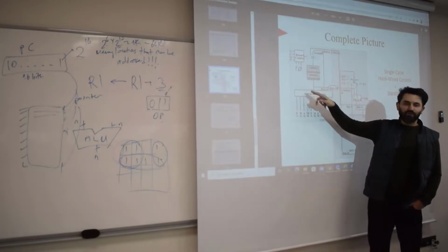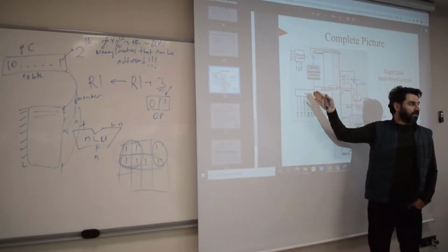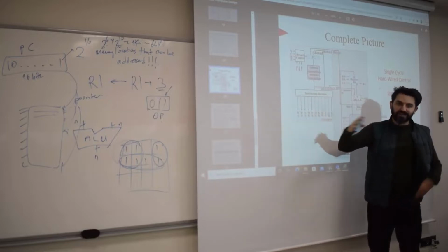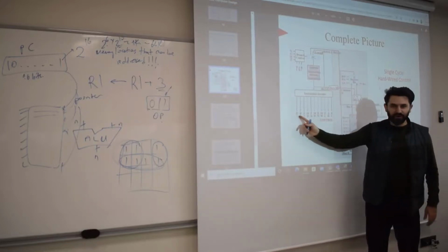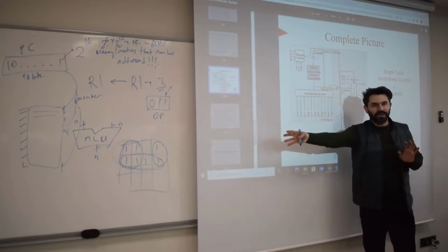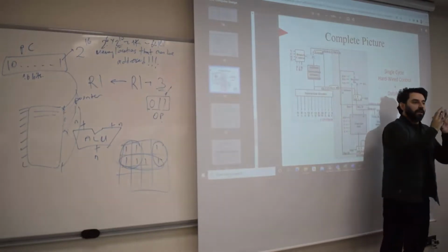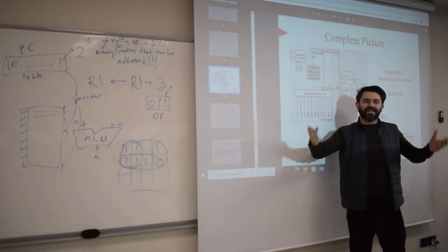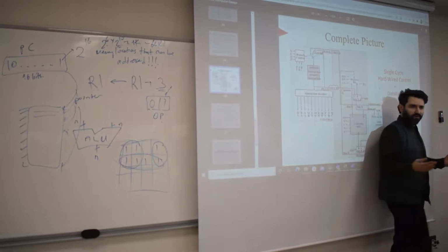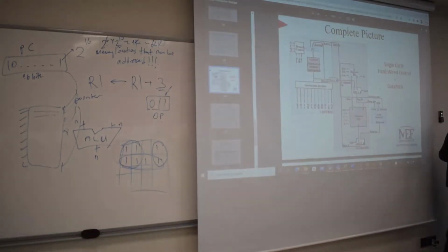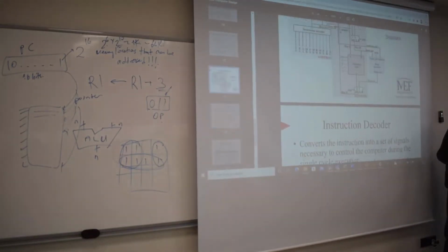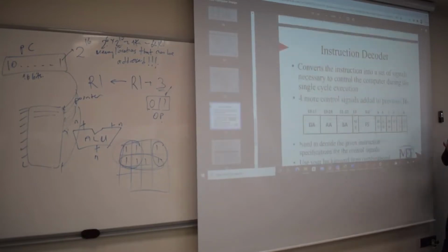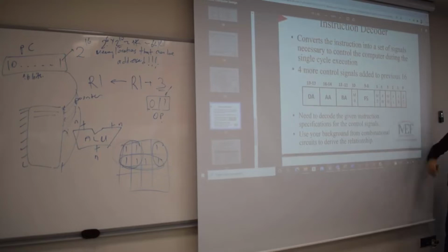You should actually draw for 16-bit inputs, that means 2 to the 16. So the Karnaugh map is 2 to the 8 by 2 to the 8. It's a huge Karnaugh map for each one of these bits, and you've got 20 of them. Not only do you have to optimize per function, but you also have to optimize across functions. So it's going to take a lot of effort, okay? But if you realize there are many simplifications already, you don't even have to go through Karnaugh map optimization.